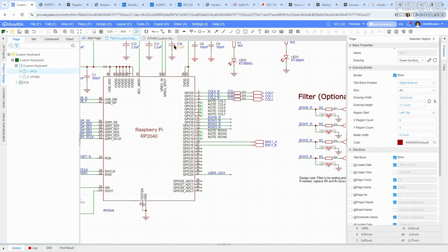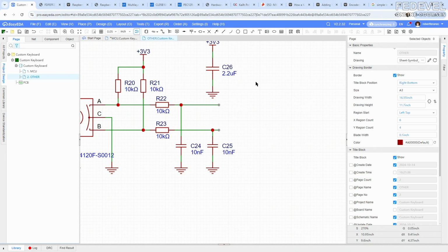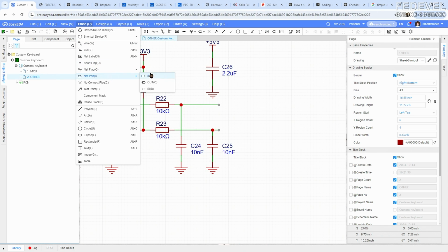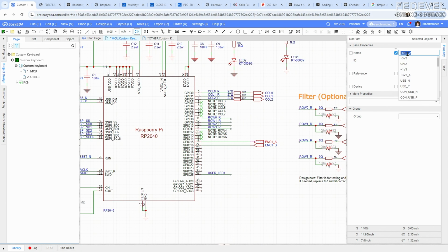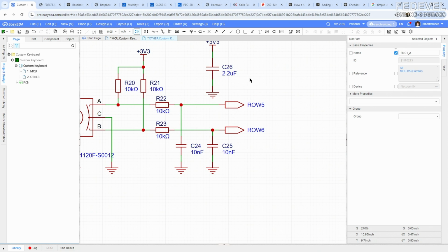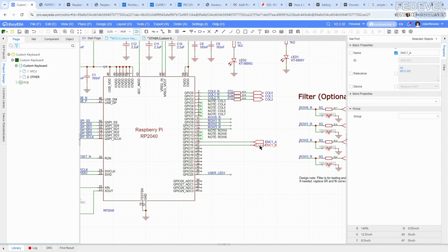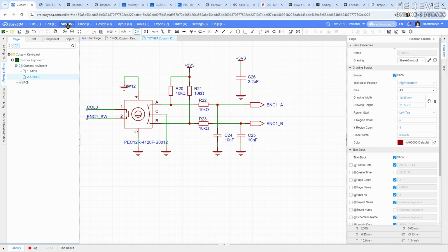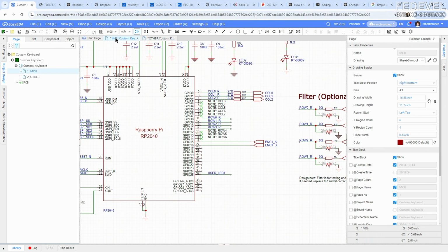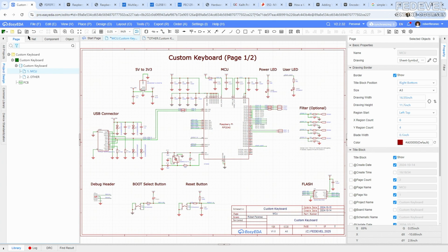the output ports on the other page, we will connect to the encoder. Okay, so go here, place the output pins here, and connect them to the microcontroller. So it means use exactly the same name. Paste it here and use the second name. Just copy it and paste it. Okay, this looks good.